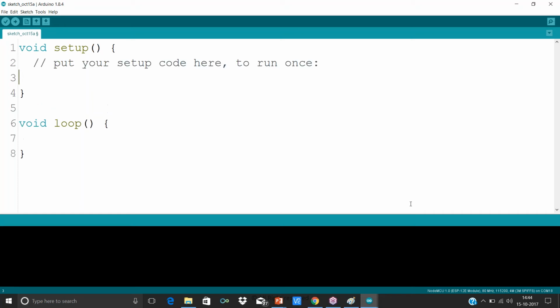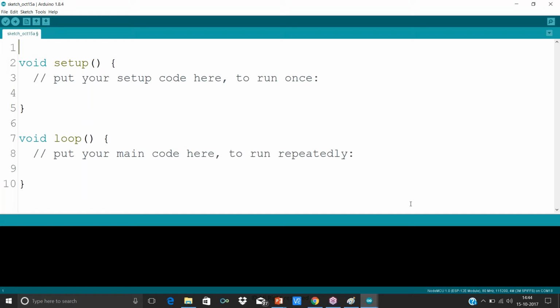Okay, so it is not necessary to remove this part as such. Here we'll define int sensorPin equal to A2. Let's say that's the sensor pin where we are going to interface the output of the sensor. A0 to A5 can only be used for analog input devices, so we do not need to define the pin mode.